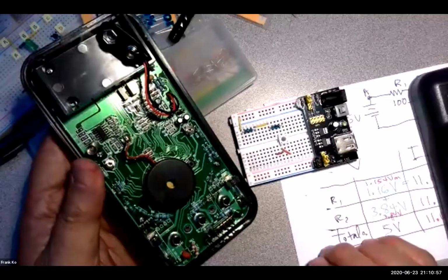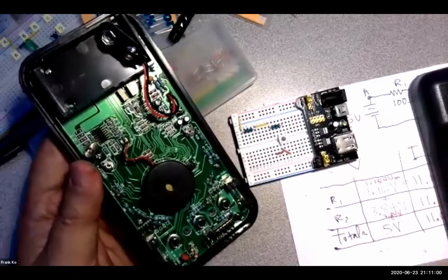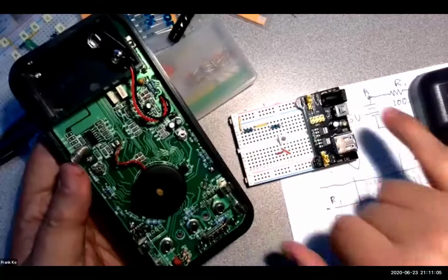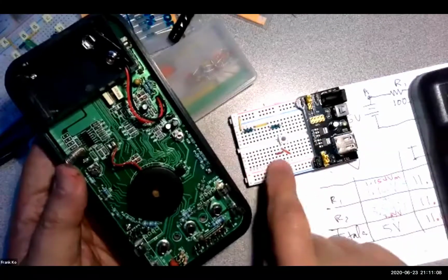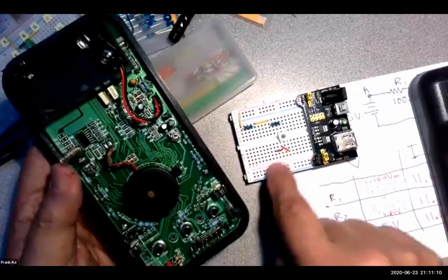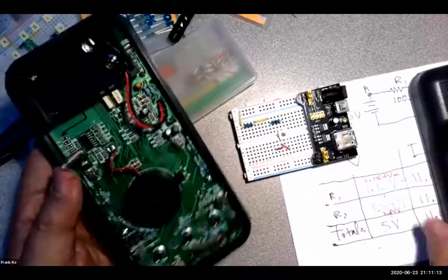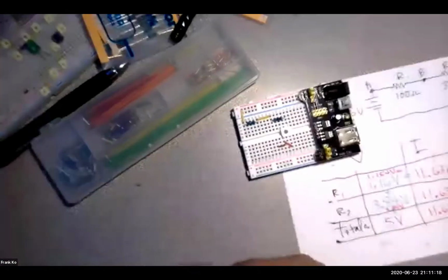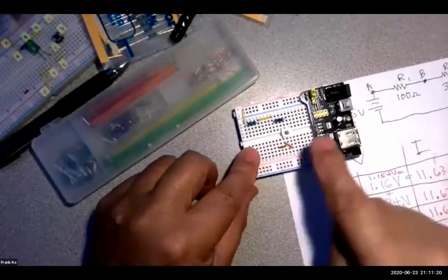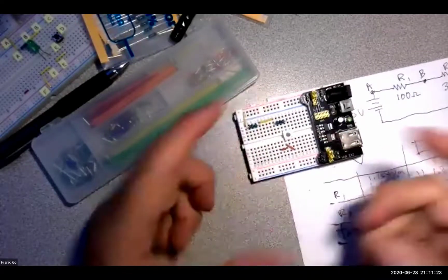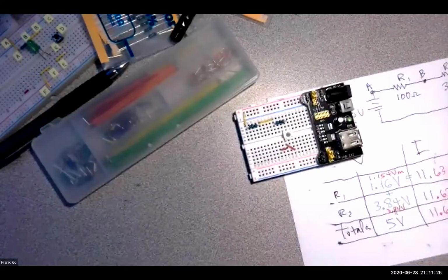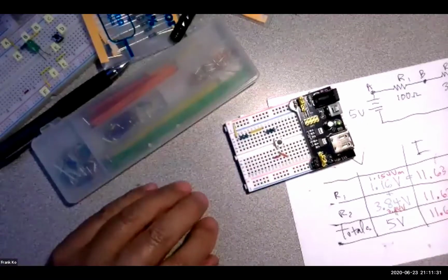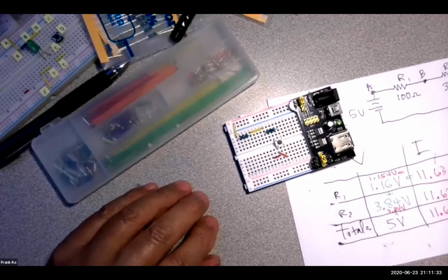Don't make any current measurements. So only measure voltage, only measure ohms. When you measure ohms, you have to make sure that the circuit not only is deactivated, unpowered, but also physically disconnected. Notice that last jumper to the negative rail has been physically removed. That's the only way you're going to measure resistance, when the circuit is de-energized and not connected to a power source. Otherwise, for voltages, just remember to use the appropriate polarities. And we'll talk more about this and many other things come Thursday.